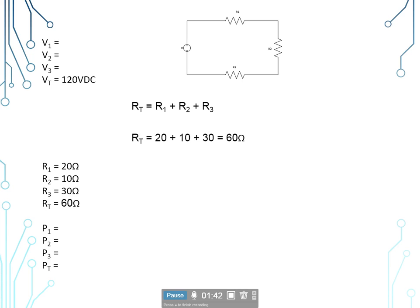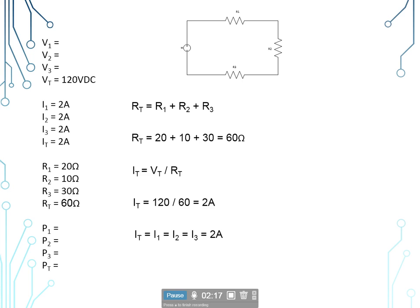Now that we have our total resistance and our total voltage, we can find our current for this circuit. So I sub t is equal to V sub t divided by R sub t. We have our total voltage of 120 volts divided by the total resistance of 60 ohms to give us 2 amps. Now in a series circuit, the current remains constant through all components. So I sub t is equal to I sub 1 is equal to I sub 2 is equal to I sub 3, in this case equal to 2 amps. So we can populate those other 3 currents for the individual components.